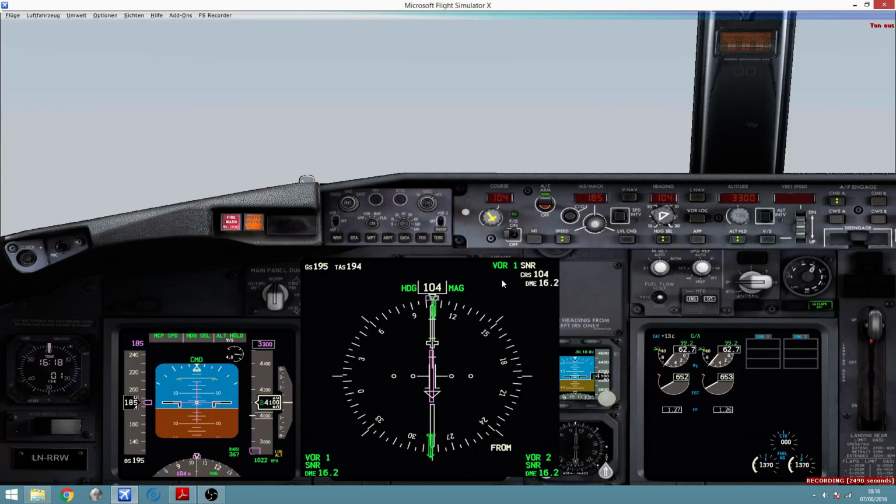It's been quite quiet now, but all of a sudden everything is going to go very, very fast. Because when we turn, we'll have to switch from VOR to ILS navigation. At the same time, we'll have to descend, reduce to 180 knots, prepare flaps 15, everything in just a few seconds.